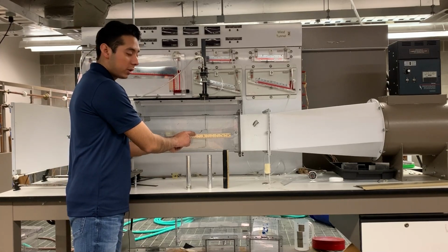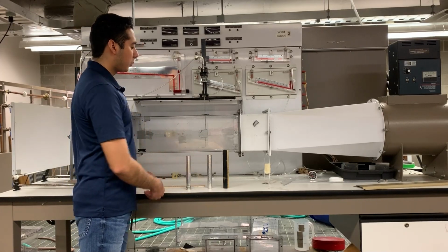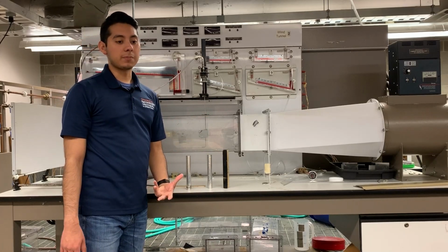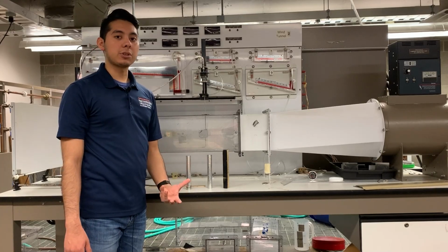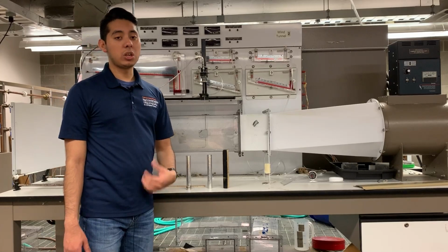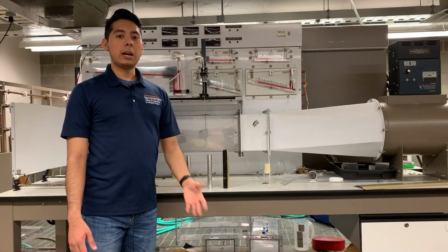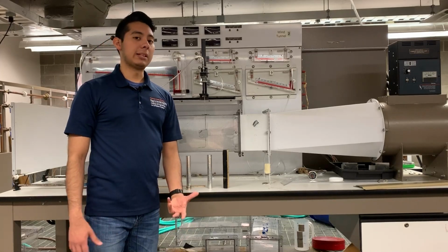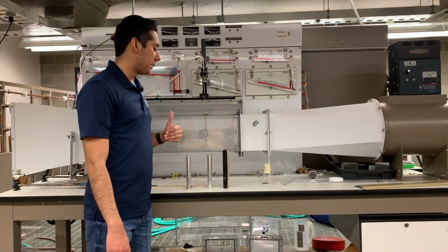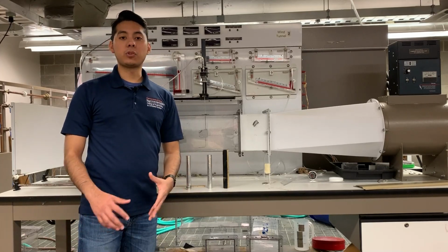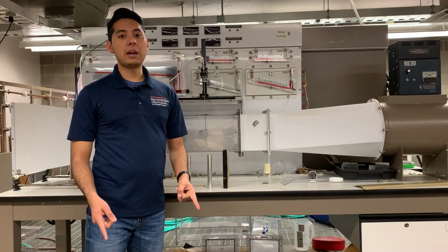away from our rod, and we're going to start measuring our pressure from the bottom to the top in increments of 1 centimeter. Once we get those pressures, we can convert them to velocity so that we can find our drag force using equation 1 and equation 2 as seen in your procedure manual. Once you get that, you will continue your analysis to determine which of these shapes experience the most drag force. So that's it for the procedures. Let's go into the lab so that we can get our results.